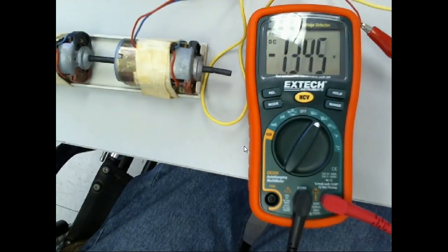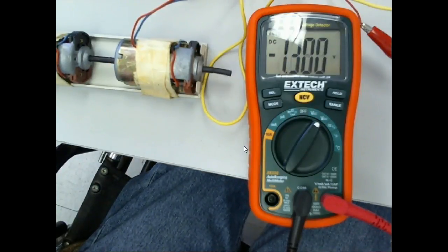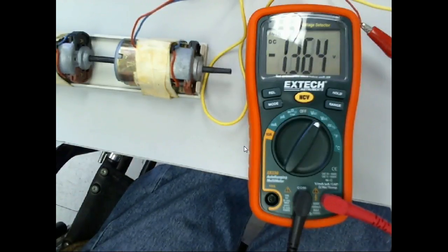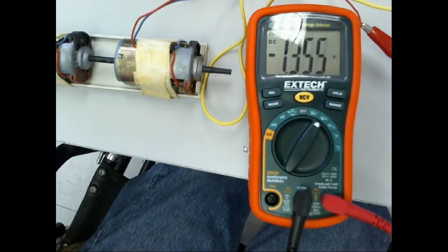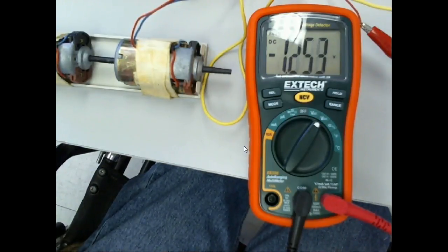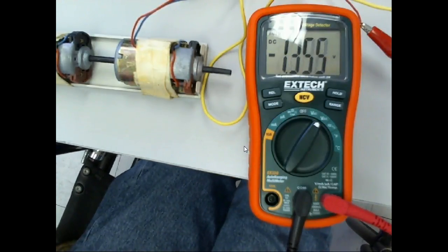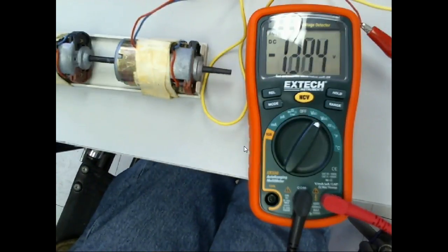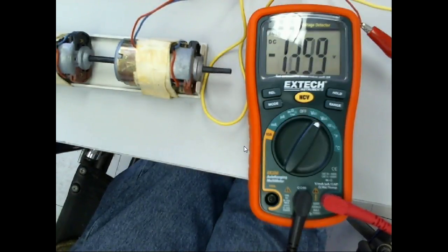If we use them to step down speed, we gain torque. So we can either use them as torque multipliers or we can use them as speed multipliers. And it's the ratio of the gears. So you can count the number of teeth on your gears and then take the output gear divided by the input gear. Gain is always out over in, right? You understand that? Or you can take the diameter of the gears, it would be your output diameter over your input diameter. Everybody understand that?